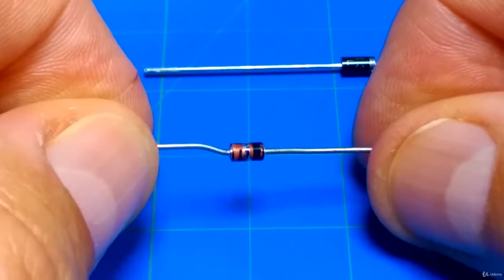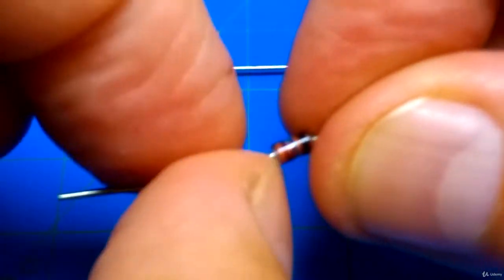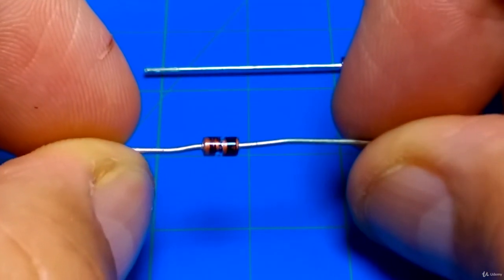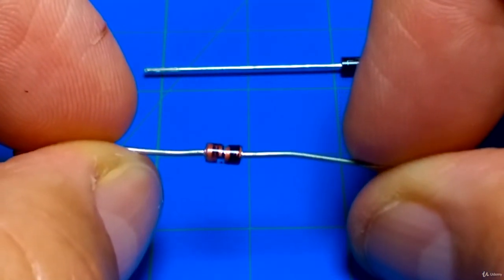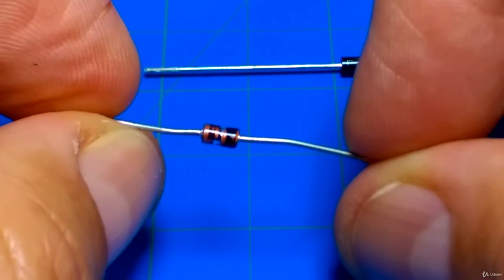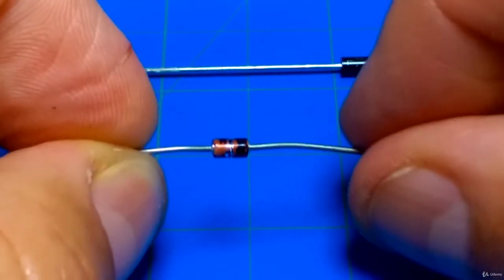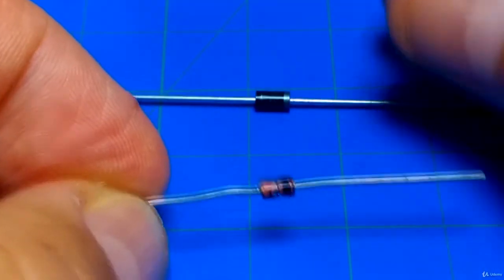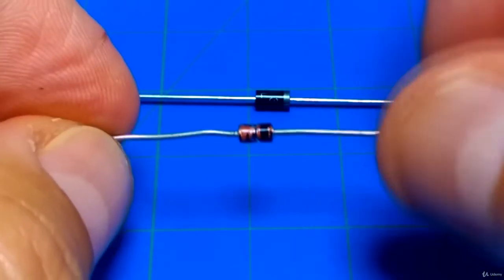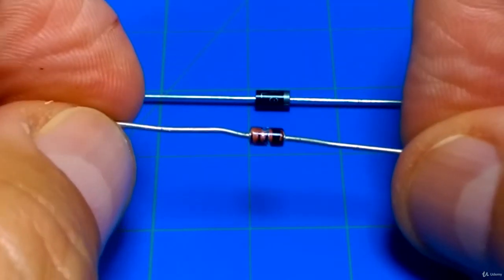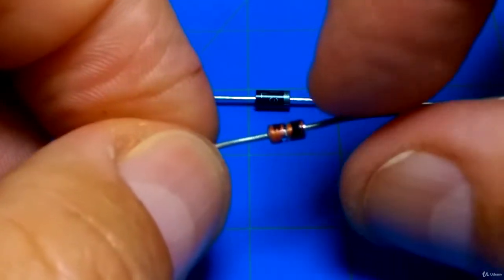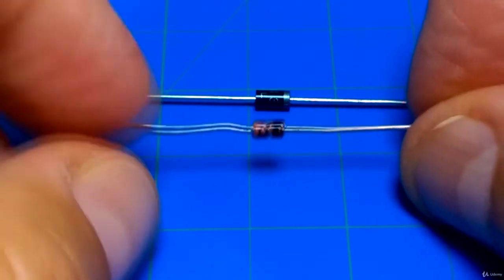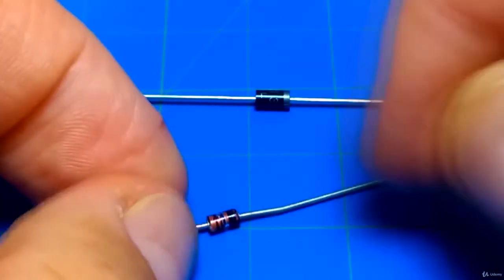And here's another diode. So this one is called a glass passivated diode. Let me bend those up a little bit, clean those up. All right, and again, you can look on it, you can see the number on it, which even under this magnification is difficult to see. But anyway, the cathode is to the right. You can see the black bar. So again, current is going to flow that way. These have slightly different properties, and the part number has to do with how much current can flow, depending on the manufacturer and voltage, things like this. Sometimes the part numbers are just completely random. All right, so anyway, those are a couple diodes, and that's what diodes look like. Again, these are axial diodes.